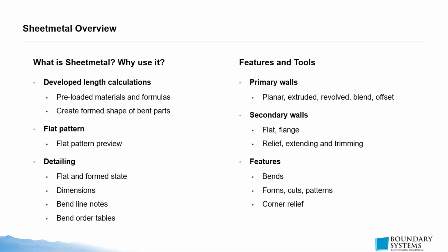As I said, I think usually the way to go, especially if you're starting from scratch, is to create a new sheet metal part. But if you are going off of something that's already created in Creo, either by one of your colleagues or by yourself for a different project, different parts, and you simply want to be able to model that using these sheet metal tools, you do always have the option to convert a part to sheet metal, and I will show you how to do that.